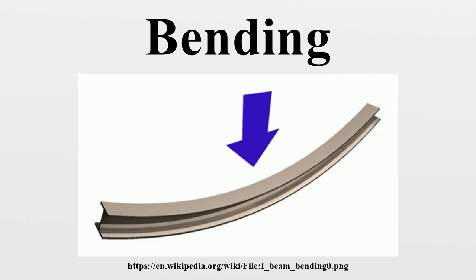Large bending deformation. For large deformations of the body, the stress in the cross-section is calculated using an extended version of this formula. First, the following assumptions must be made. Assumption of flat sections: before and after deformation, the considered section of body remains flat. Shear and normal stresses in this section that are perpendicular to the normal vector of cross-section have no influence on normal stresses that are parallel to this section.